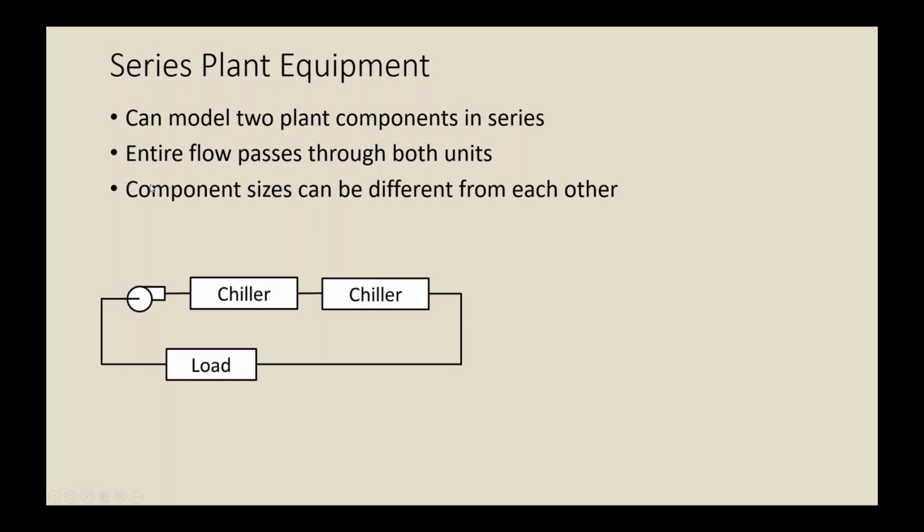So just an introduction of what it means, and for people out there who aren't familiar with series plant, basically you have a loop with plant components that are one after another in the loop, so the downstream upstream relationship. And the capabilities in DOE2 only allow an upstream and a downstream. You can have two positions in the series. You couldn't have a third one downstream of that.